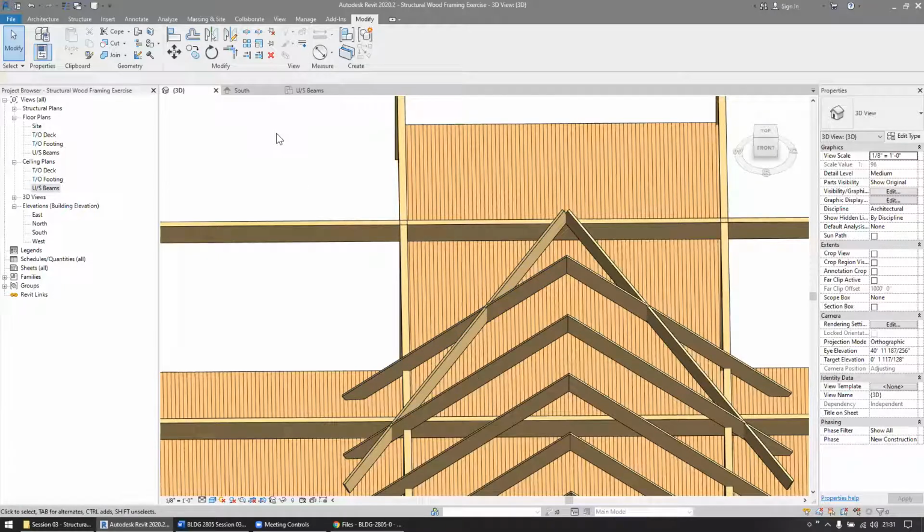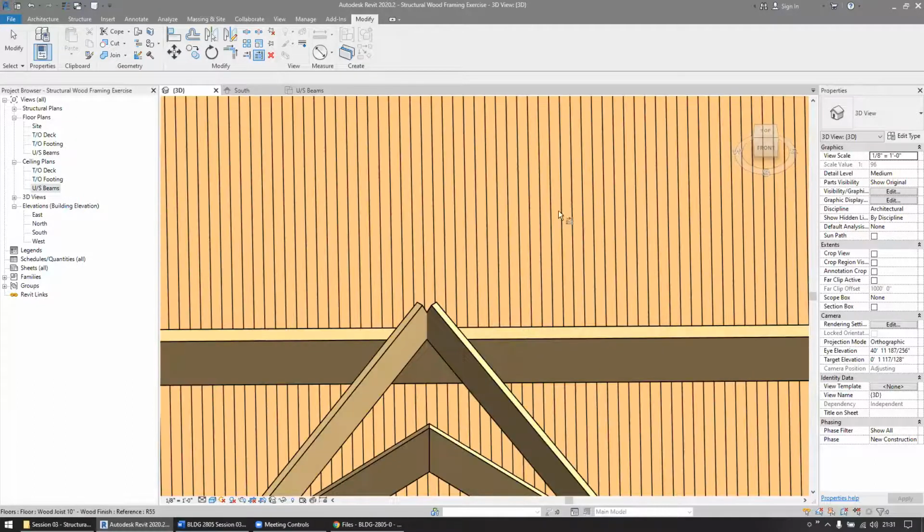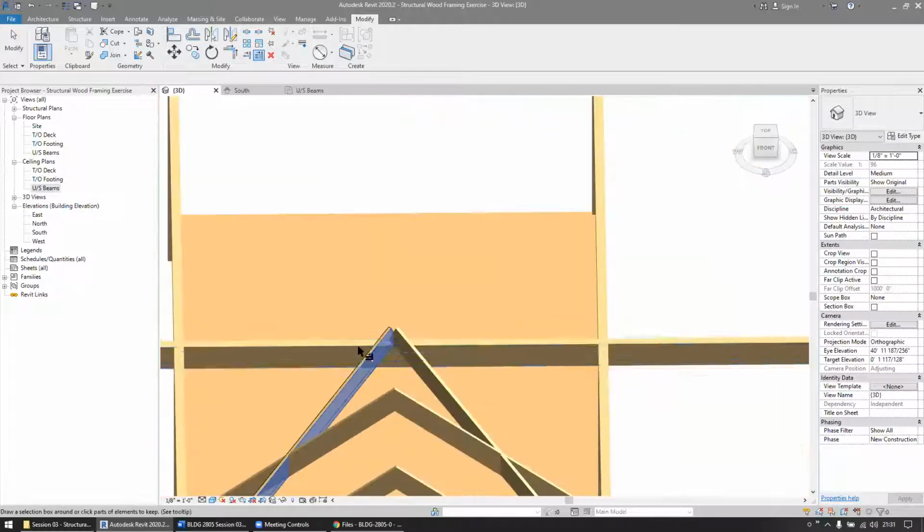So here, watch on the screen carefully as I use the extend command to facilitate this. On the modify tab, I'm using this one right here, the trim extend multiple. And what you need to do now is very carefully make sure that you pick the face of the valley rafter closest to you. So here you can see how it's turning blue. There.